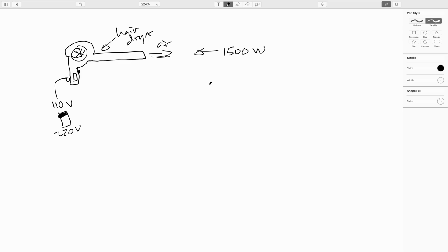What happens is they bring along the little adapter that changes the shape of the plug from an American style plug to a European style plug. And so they just plug the American plug into one end of the adapter, and then the other side goes into the outlet in Europe. But they forget to throw that 110-220 switch.